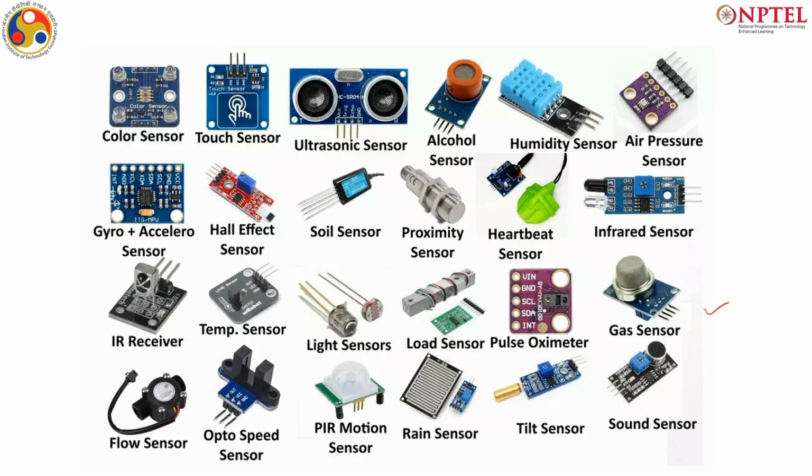So, they have the signal conditioning and the ADC built into the sensor itself. In some cases the ADC can be separate, so you have to either implement a separate ADC for interfacing, or directly integrate to a DSP or a processing unit which has an ADC with it.